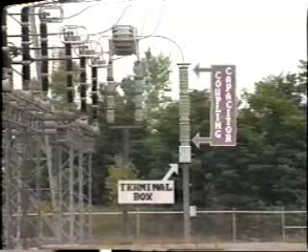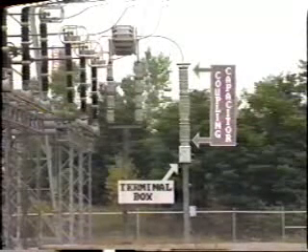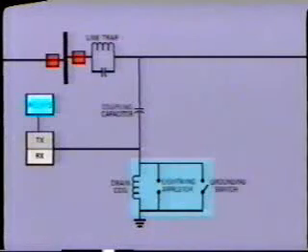However, let's focus our attention on the carrier coupling. The terminal box is often located at the base of the coupling capacitor. It contains the capacitor grounding equipment, that is, the grounding switch, the drain coil, and the protective gap.